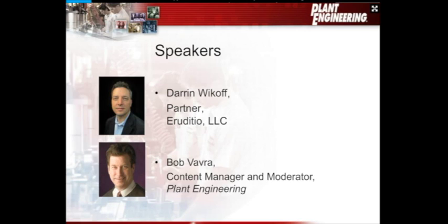Again, if I begin with the criticality analysis model and I see that spares lead time comes up in that significance analysis result, and a number of different assets are indicating that spares lead time is an issue, then I'm going to start digging into a more formal ABC classification, going through and trying to understand each component, delays, spares lead time, cost of carrying cost or cost of transaction.